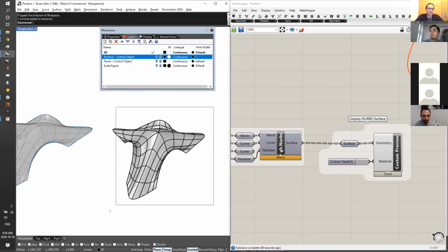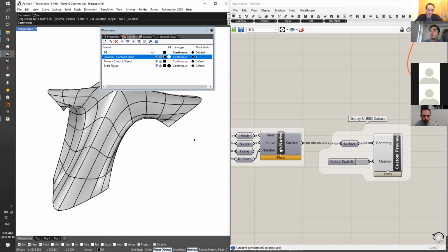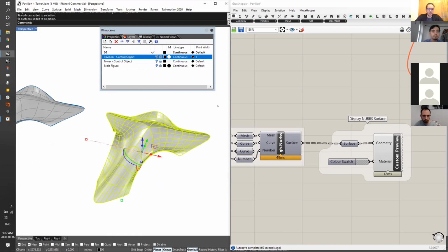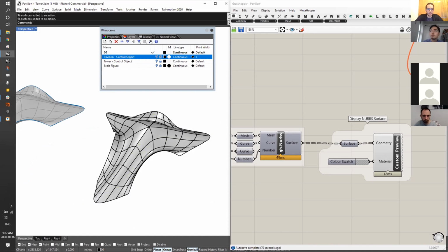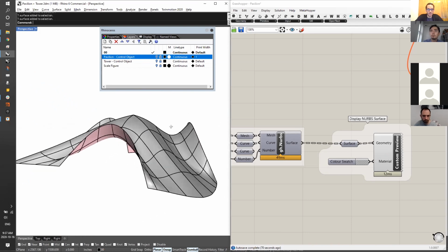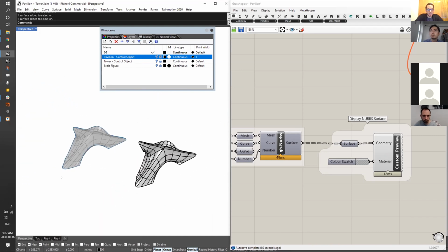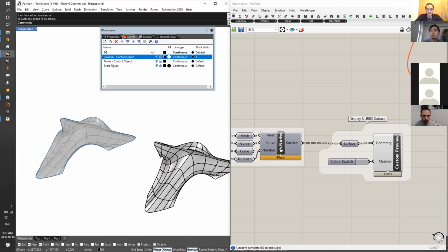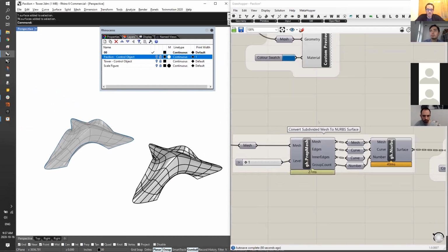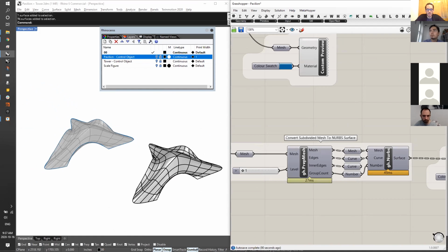That we can use for really anything. If you remember Rhino 5 days, this would have been a blessing because you can't make 2D from meshes in Rhino 5. We kind of can if you convert, but nowadays you can make 2D from meshes, but you still get a bunch of faces and a bunch of conditions. In this case, now we have clean surfaces that we can use for whatever reason. If your intent is to sculpt a quick mesh, get a surface, and then work from there, then that's already something you can do. And in the tower example, we look at how we can combine the NURBS result with the mesh result to create something like floor slabs, and then derive quote-unquote structure, something we can use to inform a general structure of it.